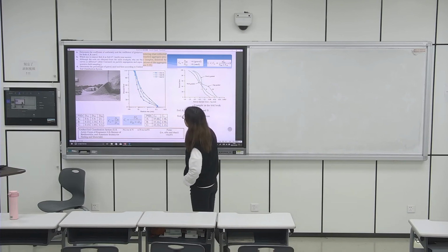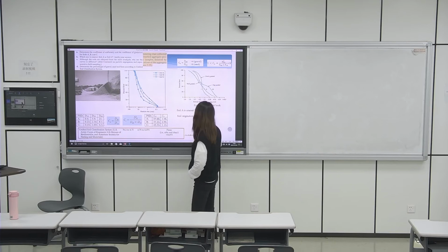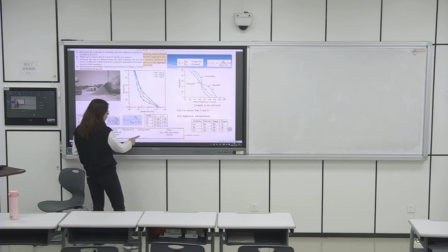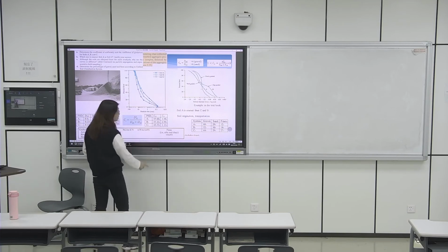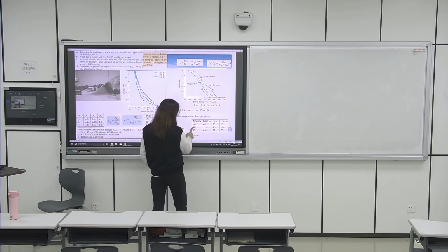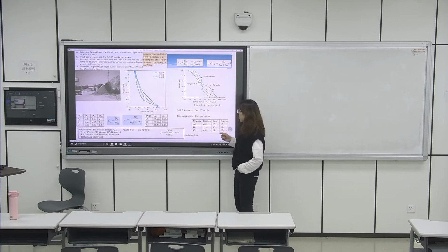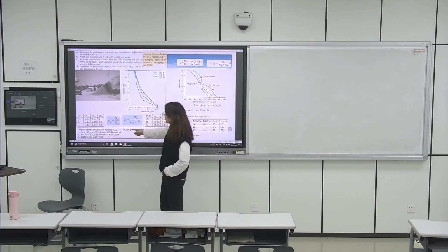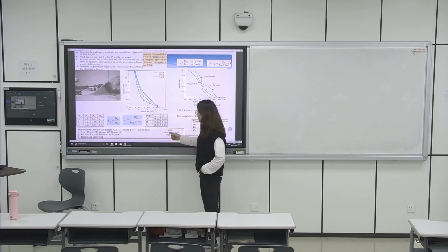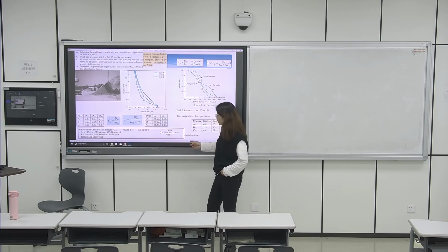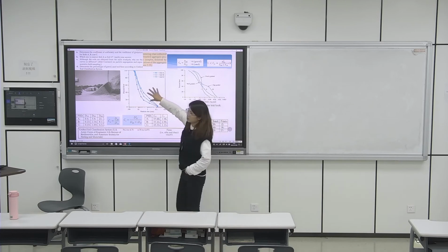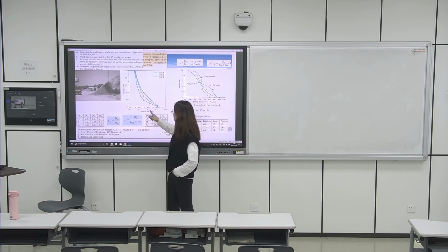The final one is determining the percentage of gravel, sand, and fines according to the Unified Soil Classification System. We have the unified classification system. This is for gravel, sand, and fines. Then just define soil A, B, C by gravel, sand, and fines. For example, for the Unified Soil Classification System, fines means particles less than 0.075 millimeter, right? Then go to this figure to find the 0.075.